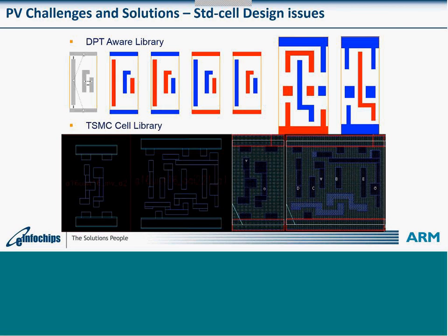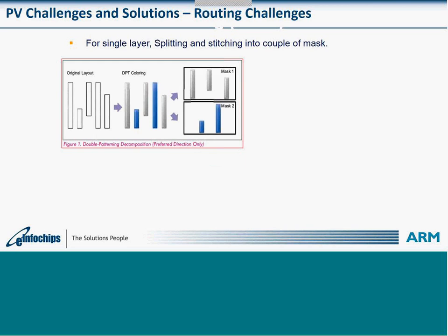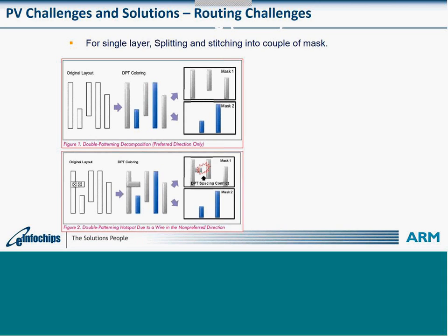Now the next one: routing challenges in PNR digital implementation. If there are only straight lines spaced at minimum distance, it is very easy to differentiate them into two different masks. There is not a big challenge, but early phase PNR tools were smart enough that they dropped a lot of jogged wires on lines when connecting to higher metal layers, and that started creating related issues.